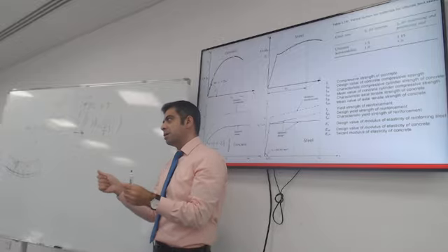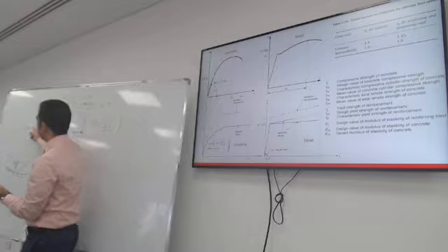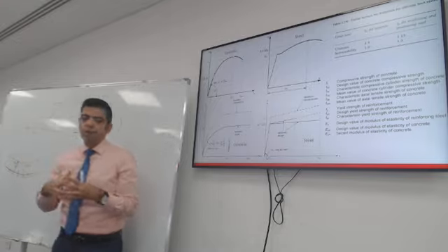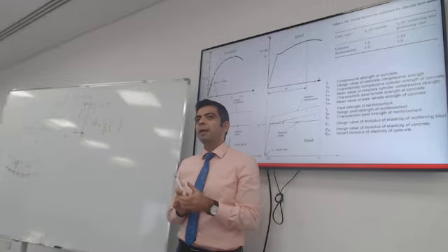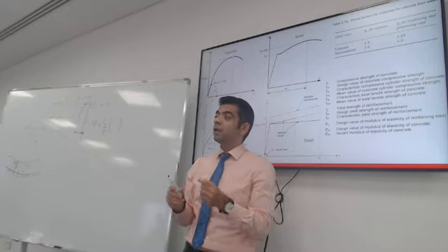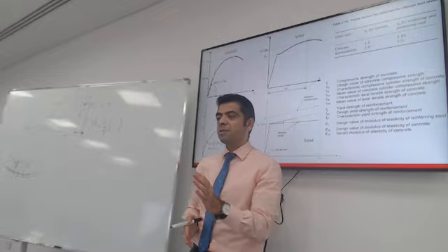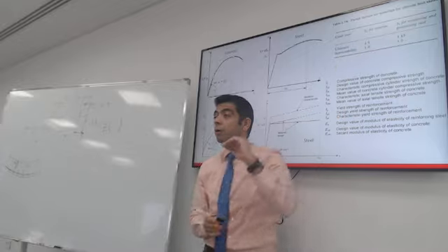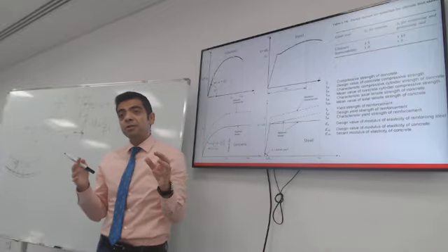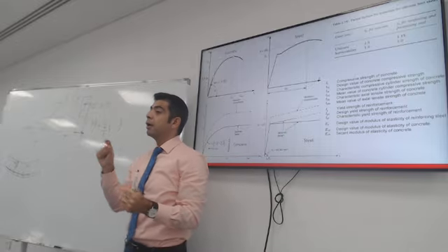Someone could use the wrong dimension. Someone could miss a bar. Someone could miss the cover. The cover could be higher than it is or lower than it is. There are more variables that need a little bit higher factor of safety. So it's a good eye that you spotted the difference in the material factor of safety between steel structures and reinforced concrete. The reason why the partial factor of safety for reinforced concrete is higher than steel structures is because there is more variation when it comes to reinforcing concrete with bars.